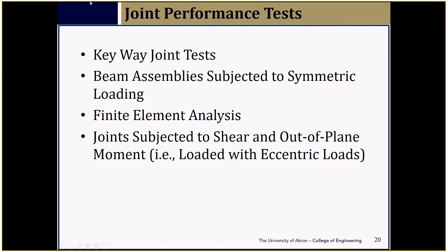Therefore, we try to understand the factors influencing joint performance with keyway joint tests, which are smaller tests. Then we down-selected our variables to go to the next level, which is large beam tests. Beam assembly tests with symmetric loading is one type of test we performed in the study.